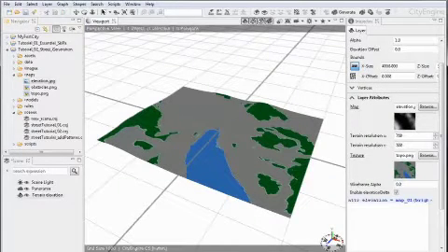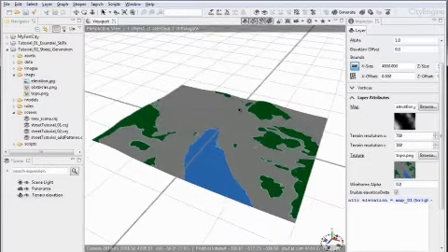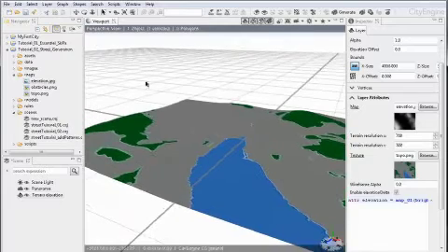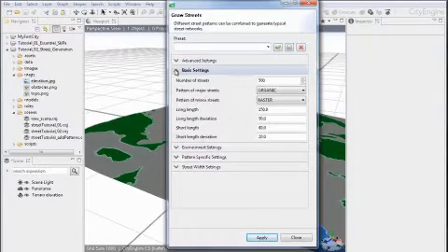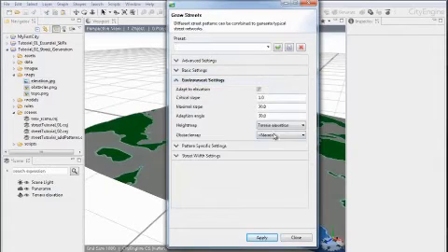In this second part of the tutorial, we are again going to grow some streets and talk about the obstacle maps. So let's go in and trigger again the Grow Streets dialog. Now under the environment settings, what we can do, or it was done already automatically here, is CityEngine took the actual terrain. So we can choose the height map and use this as an input for the Grow Streets dialog.